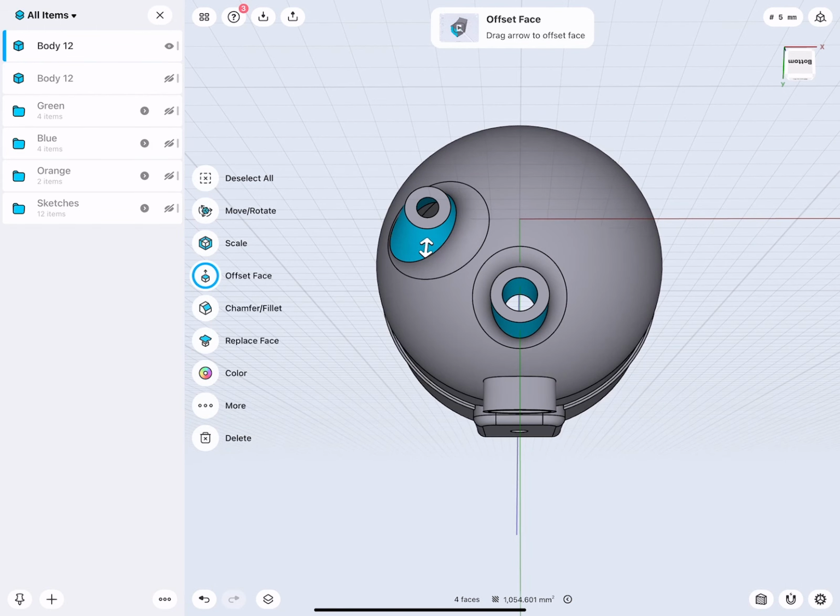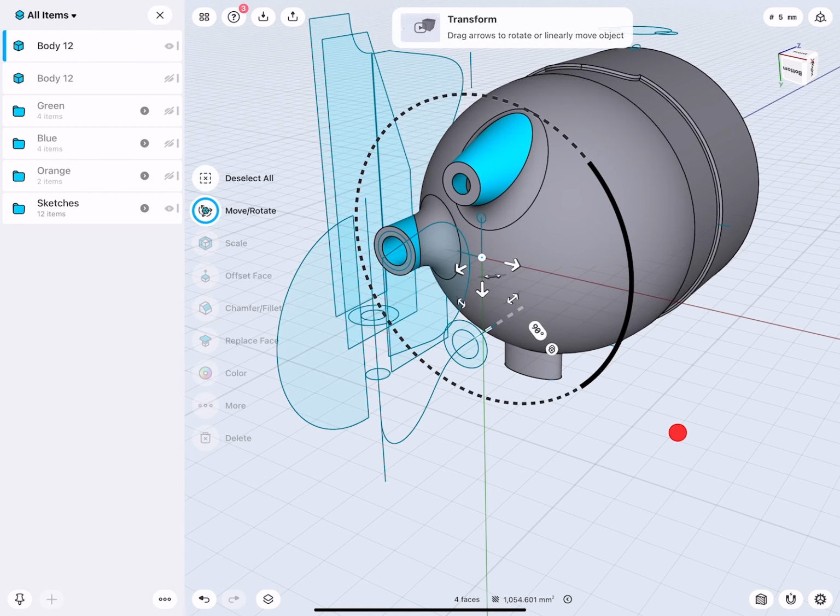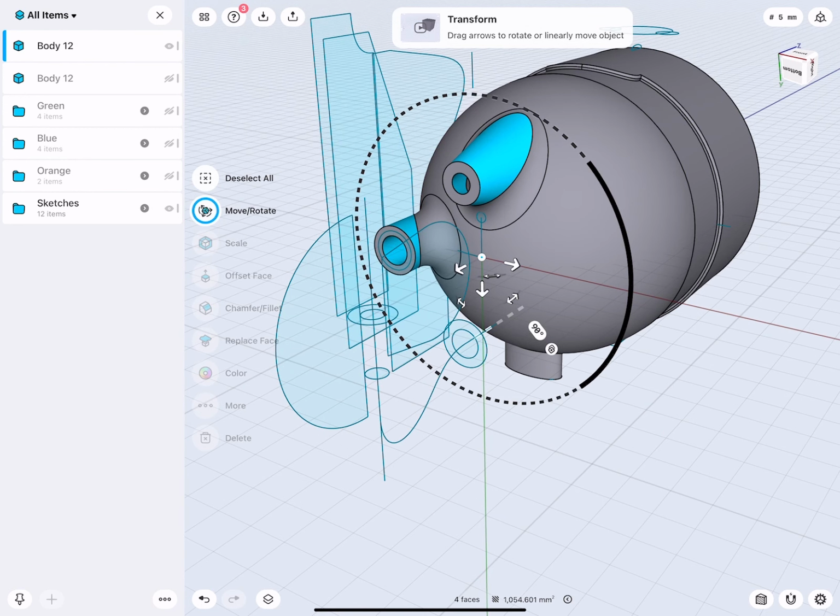So I turned on the sketch. You see then you get better snapping abilities. And check this out now. How I'm rotating this and everything follows. How cool is that? So you see, you don't need to have multiple sketches when something like this can be rotated around a shared axis. Sketch in one time and then just move your copies. Perfect.